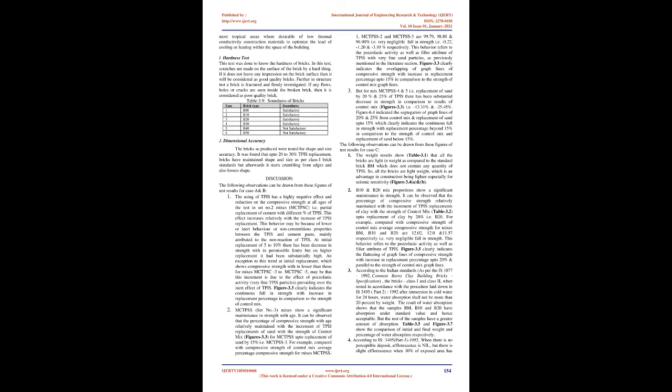3. According to the Indian standards, as per the IS 1077, 1992, common burnt clay building bricks, specification, the bricks, Class I and Class II, when tested in accordance with the procedure laid down in IS 3495, Part 2, 1992, after immersion in cold water for 24 hours, water absorption shall not be more than 20% by weight.